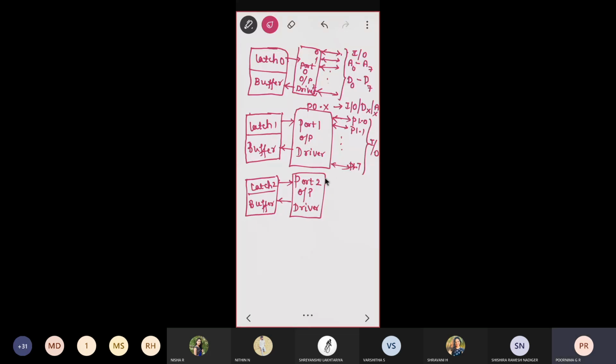And since it is multiplexed, each pin is represented as P2.0, etc. It is multiplexed with A8, etc. The 0th to 7th pins of port 2 are multiplexed with address. Therefore, the last pin of port 2, P2.7, is with A15.